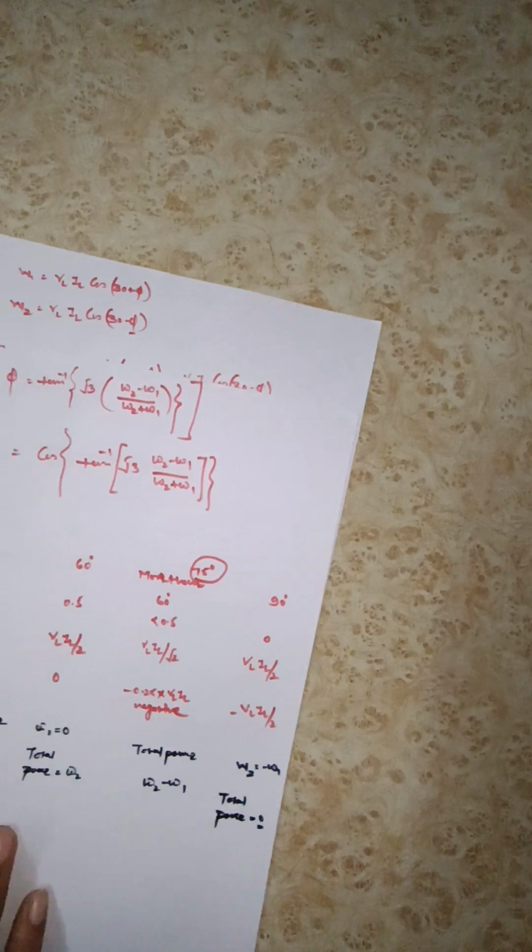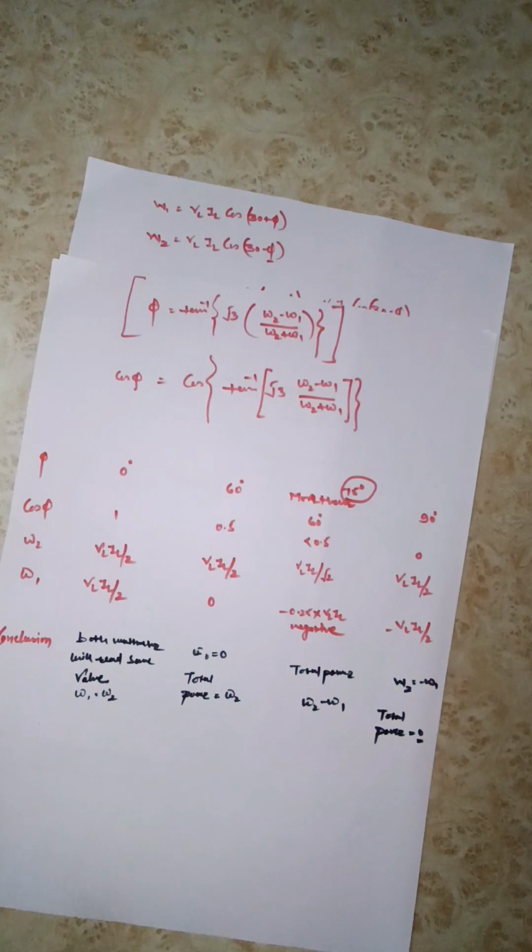So this is all about the 2 wattmeter method. Okay. So you have to remember this formula, how we can apply the 2 wattmeter method for power measurement, what will be the value of power, and how to calculate the phase angle and then power factor for the load.